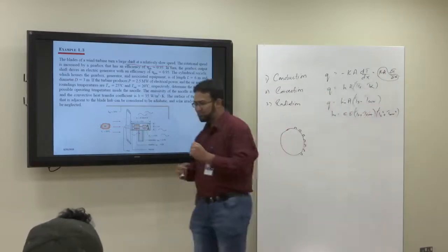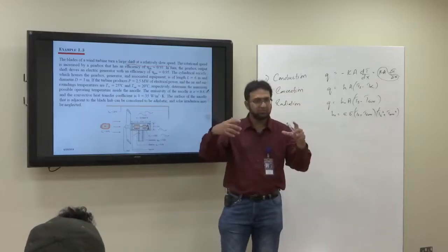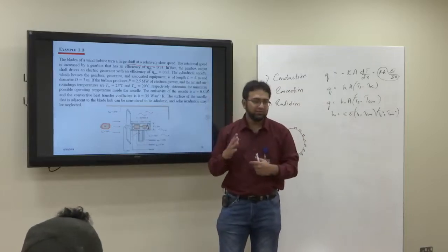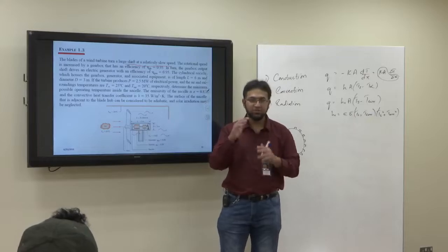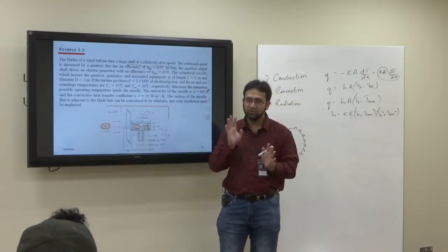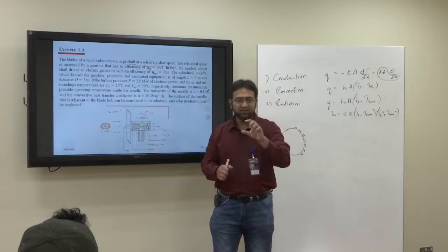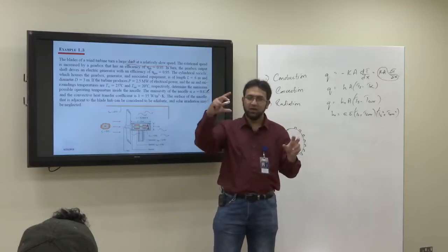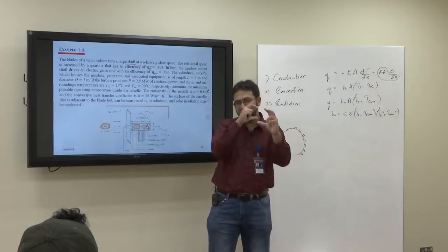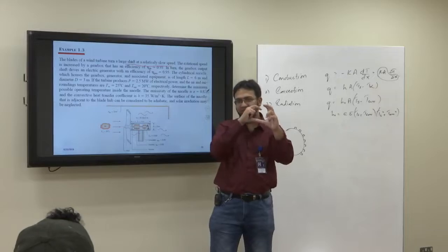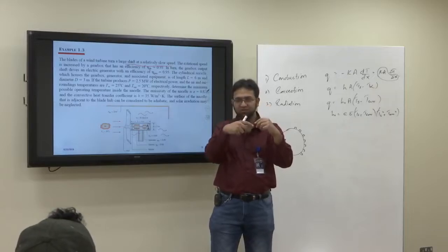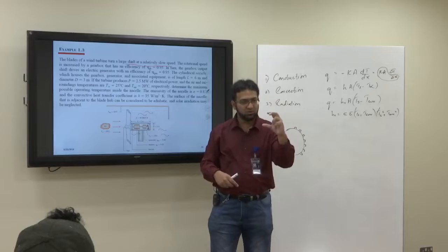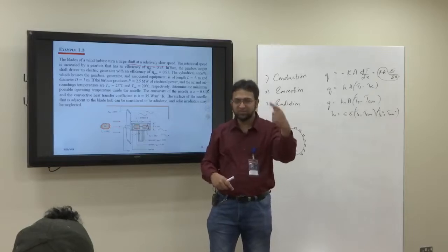So the thing is that you have a very big shaft, but it is rotating slowly. If it is connected directly to the generator, it will not produce much electricity. So what you do is connect it with a gearbox where a big gear is connected with a small gear, and when they are meshed together and rotate together, because the small gear has a small size, it will run fast.